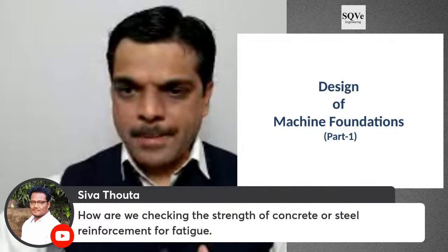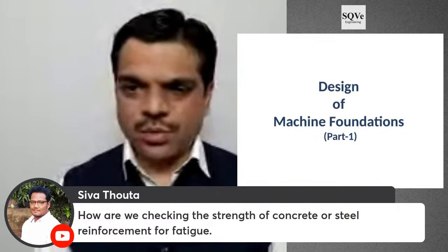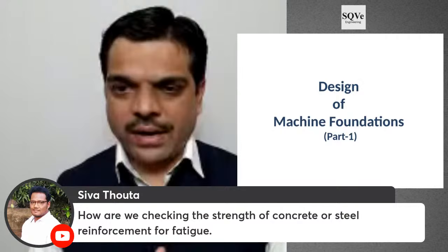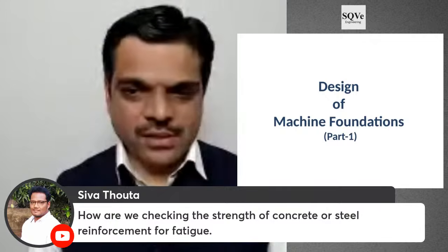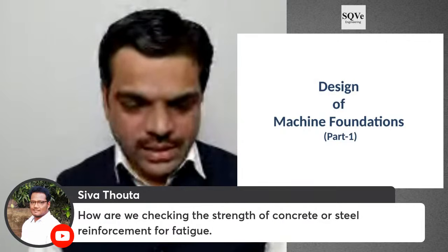Siva is asking, how are we checking the strength of concrete or steel reinforcement for fatigue? That's a good question. For fatigue, in IS 2974 the factor is given as 2 for the kind of foundation we are discussing. That factor needs to be applied while doing the static design.